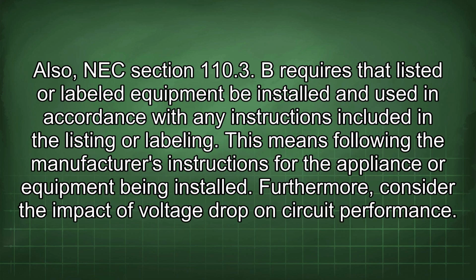Also, NEC Section 110.3(B) requires that listed or labeled equipment be installed and used in accordance with any instructions included in the listing or labeling. This means following the manufacturer's instructions for the appliance or equipment being installed.